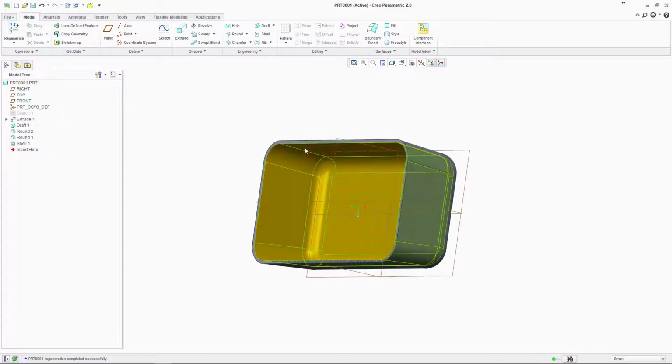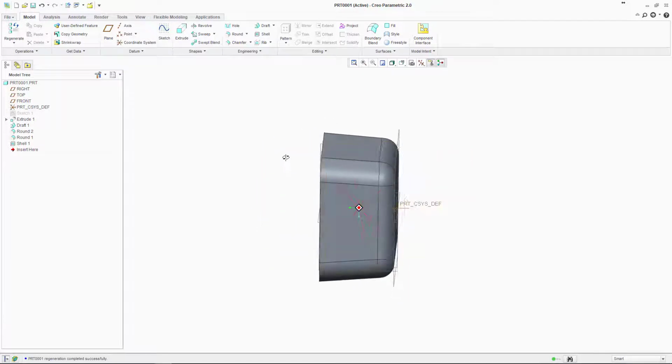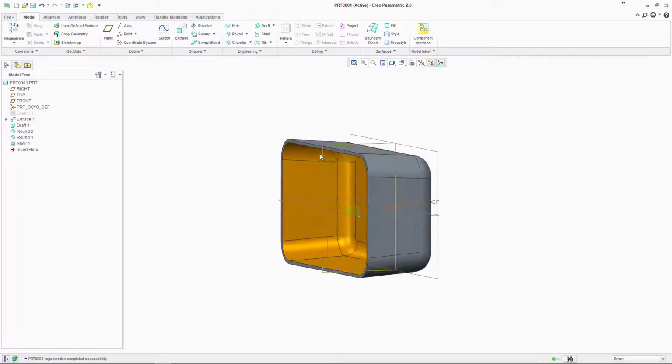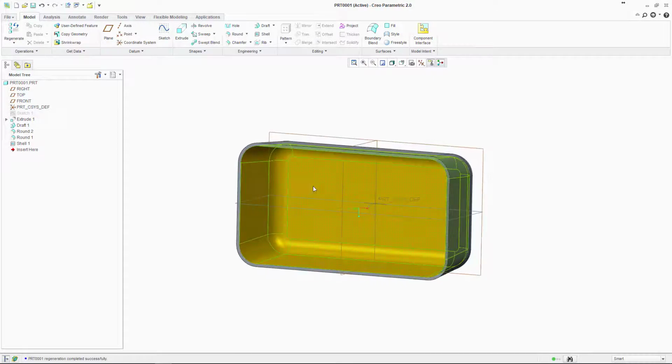But the part would come off this half of the mold quite easily, because this part has been given walls which have an angle on them. So the angle allows you to remove this part from the mold quite easily. Whereas if these upright surfaces on our part were at 90 degrees, they could grip slightly onto this half of the molding tool, and it would be hard to remove them. You would need some pins pushing quite hard to get them off.